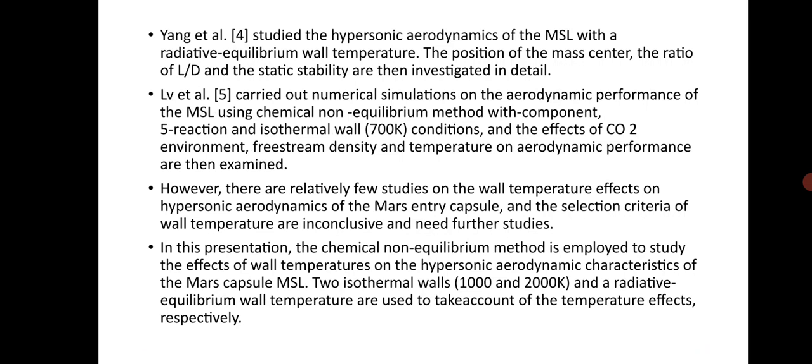Young et al. studied the hypersonic aerodynamics of MSL with a reactive equilibrium wall temperature. The position of mass center, the ratio of L by D, and the static stability are then investigated in detail. Lv et al. carried out numerical simulation on the aerodynamic performance of the MSL using chemical non-equilibrium method with component 5 reaction and isothermal wall 700 Kelvin conditions, and the effects of CO2 environment, free stream density, and temperature on aerodynamic performance are then examined.